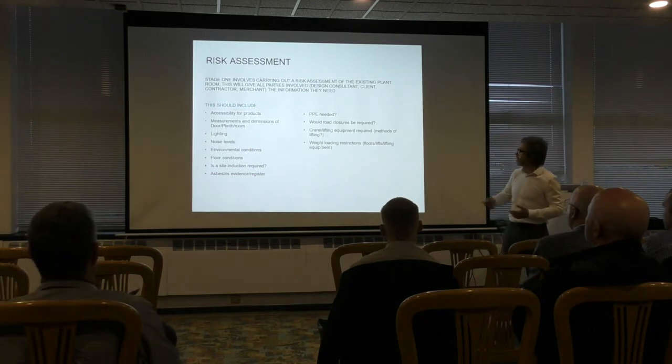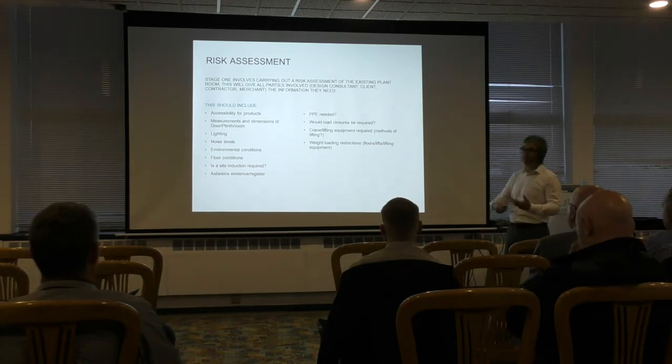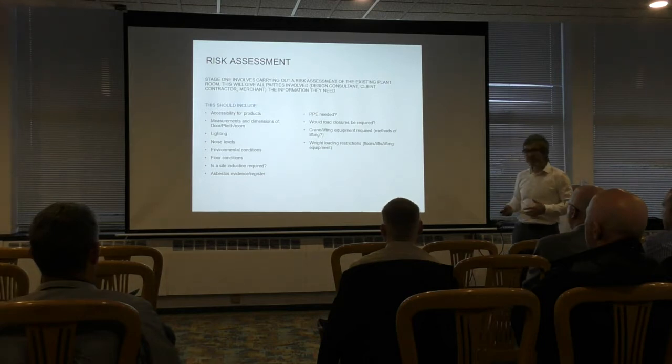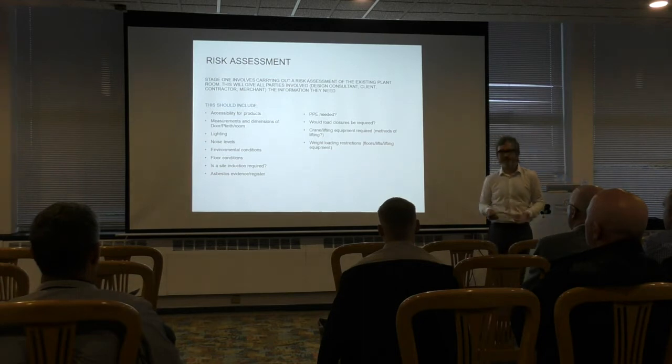But by doing that, measuring things like doorways, plinths, etc., looking at the lighting, so lighting within the plant room, lighting along the way, do we need to address that? Noise levels as well, not just noise levels inside the building, but things that we're going to be creating when we're doing that replacement. So we might need to look at things like out of hours working, if it's particularly sensitive to that. The environmental conditions along the way, the floor conditions as well. If we're looking at an existing building, there could be trip hazards, for example. Is a site induction required? Probably 9 times out of 10 we have to do a site induction on most sites.